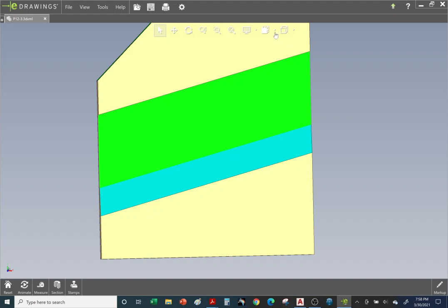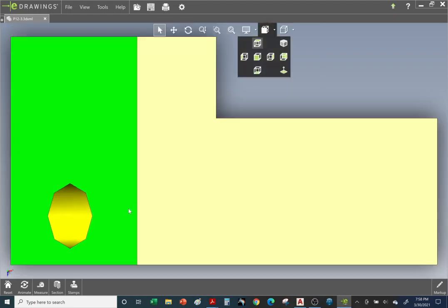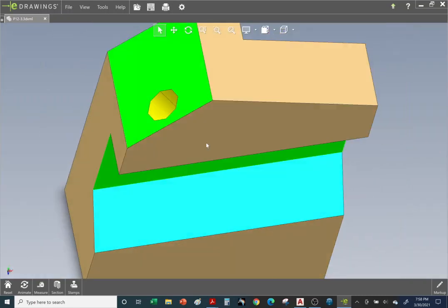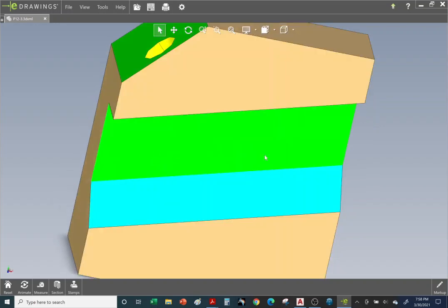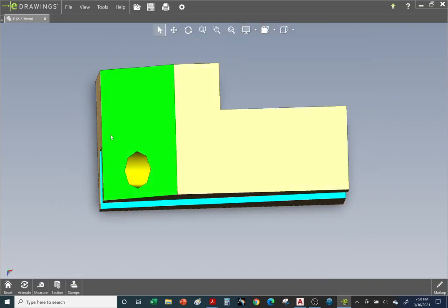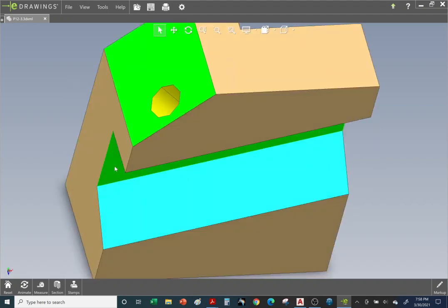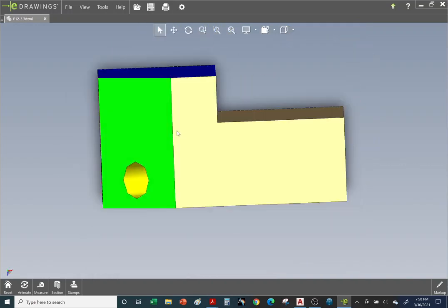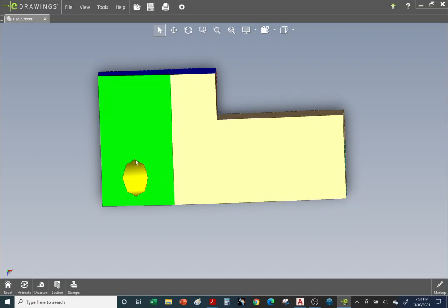Take a look at the 3D model. Top view. From the top, we need to draw the hole and also the exit. We need to draw this line. And we also need to represent the slot. From the top view, we cannot see this slot here, right? Can't see it, so we need to represent it with the hidden line going across. Let's take care of some of this geometry first, like the red hidden line for the slot going across this object line. And then we'll come back and take care of the hole. That's a little bit more challenging.